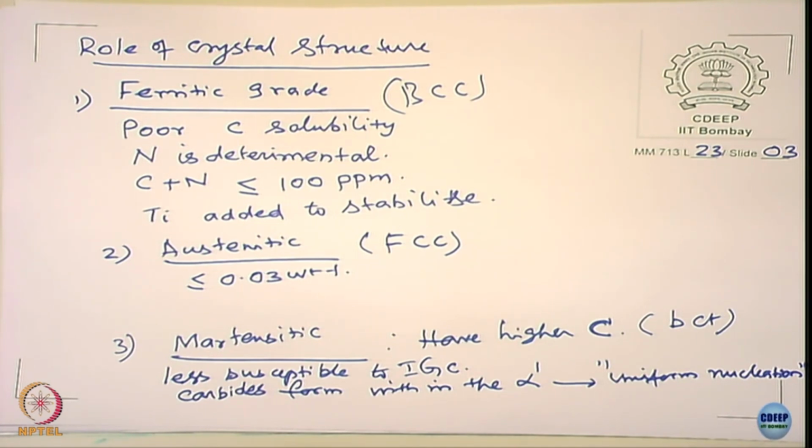So, the chromium carbide occurs all through. Okay. Now, please understand IGC occurs only when the chromium depletion occurs at the grain boundary area. That will happen only when the chromium carbide forms at the grain boundary area. If it forms everywhere, IGC does not occur. Of course, the chromium carbide formation by itself can bring down the passivity. We know that, right? Because the matrix chromium content comes down, passivity is lost, I am sure.